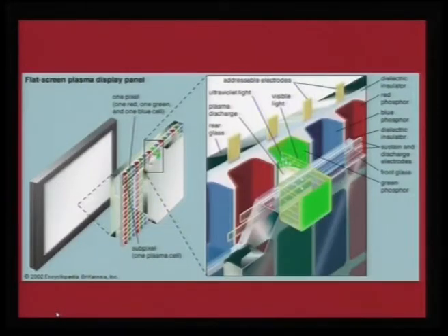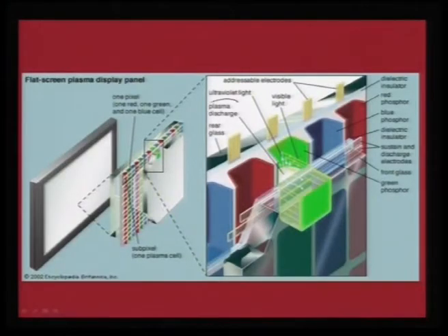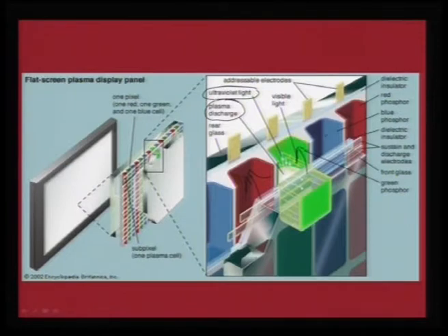This same phosphor can also be used for plasma display panels, and as you would see, the display mechanism is quite different compared to the CRT applications. In this case what you see is a plasma discharge, and this plasma discharge is actually brought about by the UV light, and once UV light is generated in the back panel, that UV light will shine on the respective ones, red, green and blue, and as a result you will get a plasma which is generated that will account for the emission of full color display.